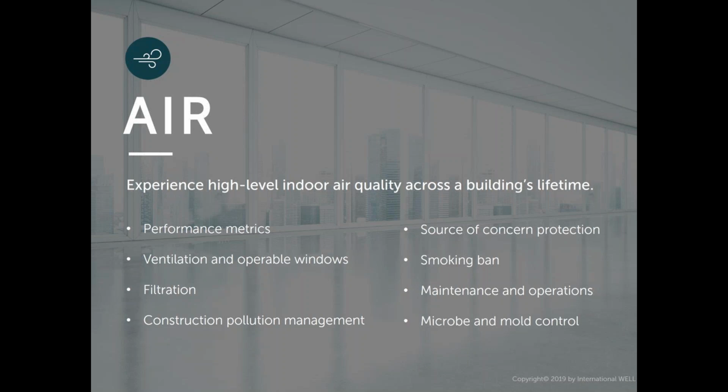Every material has a certain buffering capacity, and depending on the dynamics of the moisture conditions in the air, you don't want that moisture to migrate out and cause potential problems with clean zones, contaminants, microbial proliferation, so fungal growth, all of these types of things. You want a high level of control depending on the type of lab space in particular. And so the construction pollution management section has quite a few strategies that go, I would say, beyond what LEED has traditionally prescribed to help make this achievable. And I have seen this implemented, not in a lab, but in a high performance healthcare space, and it was quite successfully done.